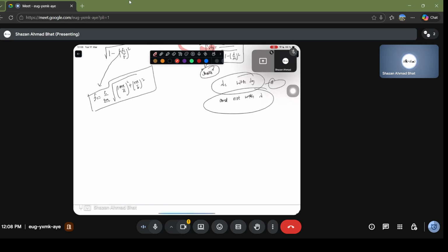Essentially it depends upon some sort of a wave vector in the x direction, and this is the wave vector in the y direction. So fc is c over 2 pi times the square root of kx squared plus ky squared. Because you have a waveguide, this will be the kx, let's say, the wave vector in this direction, and then this will be the ky direction. This is basically the z direction, the propagation direction.